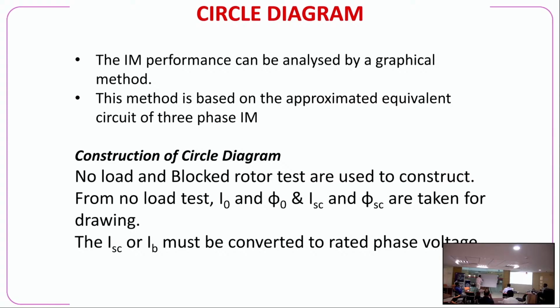Voltage is V rated, divided by VSC, into the current IFL. It is a straight line, basically passing through the origin.